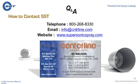Another excellent question. Cold spray is actually an excellent candidate to substitute for hot dip galvanized processes. From an economical point of view, hot dip galvanizing is fairly economical. In other words, you can hot dip some very large pieces and coat quite a large surface area per dip, depending on the mechanical configuration of the parts. And most engineers design parts with certain gas escape ways, bleeder lines, etc., so that it optimizes the galvanized coating. However, if you're doing post-operations on your galvanized part, if you're welding, if you have damage, if you lost some of the galvanized coating, it is so easy to use the SST equipment. You would simply blast the defective area using 80 grit blast media and reapply a pure zinc coating back on the surface. Mark, it's just as easy as that to repair galvanized surfaces.